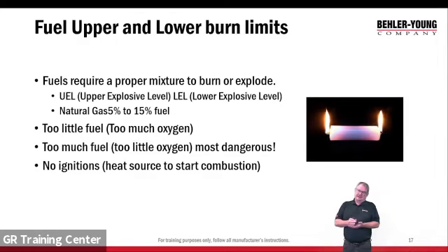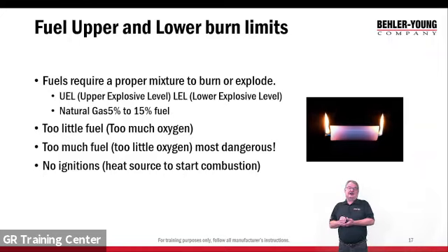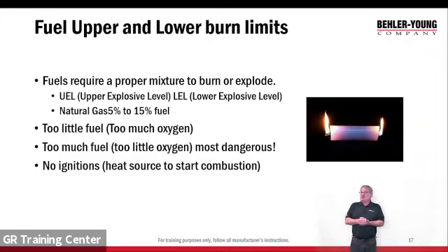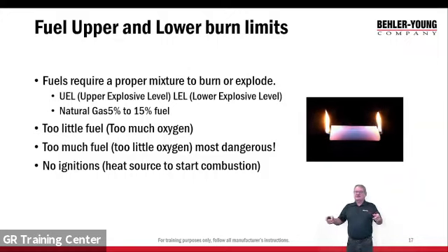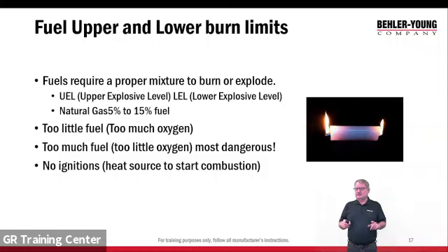Now, if we continue to add gas to that room, and let's say the amount of gas in the room you're in gets up beyond 15%. So now there's 15 or 18, 20% natural gas in the room you're in. Now it won't ignite anymore, because now it's too much fuel. That's a real dangerous one though, because what happens? It's at 20% fuel. You open the door, that fuel starts to leak out, that percentage starts to drop, we get down below 15%, and now we're explosive. Okay, so that's the upper and lower explosive limits, and we're going to talk about that with the different fuels we work with.